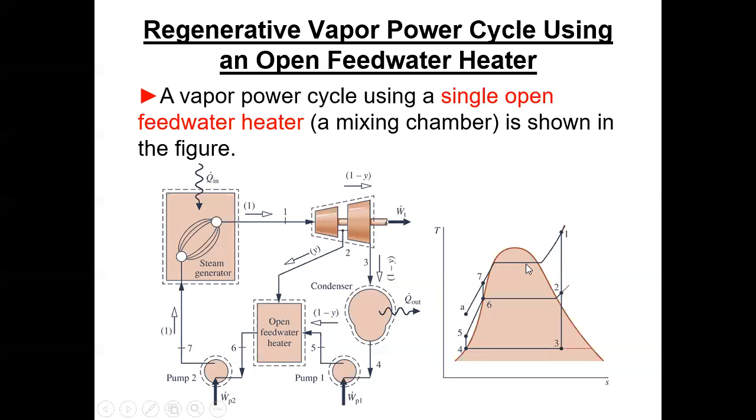And I'm also guessing that the work required for pump 2 is also offset by the efficiency gains. Yeah, because we're pumping a liquid, relative to the other energy flows at the boiler, the heat input in the boiler and the output of the turbine, these pump things are 1.5%, something like that. So the pump work is pretty negligible.